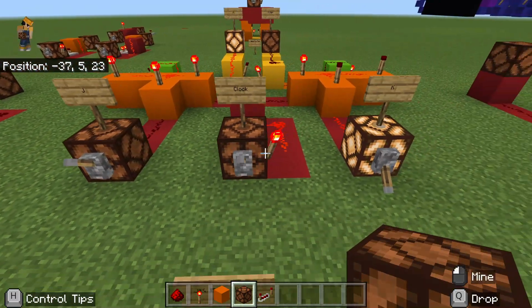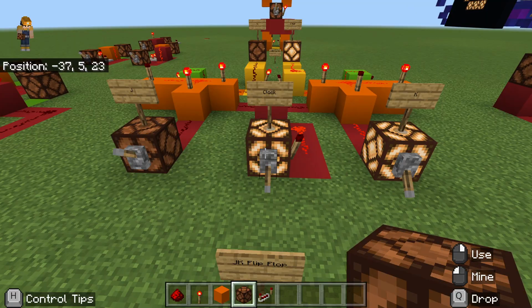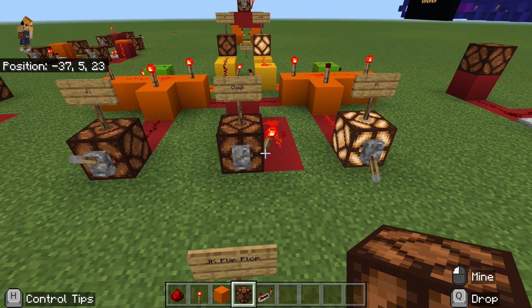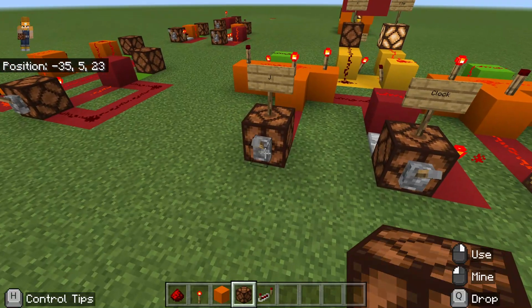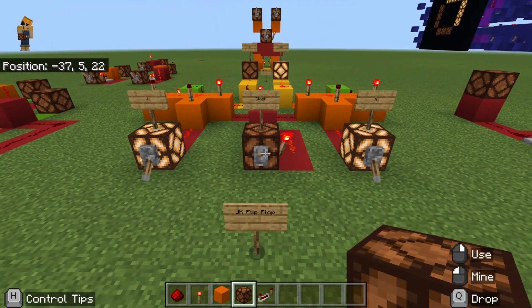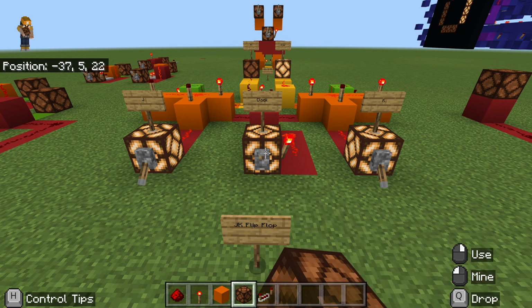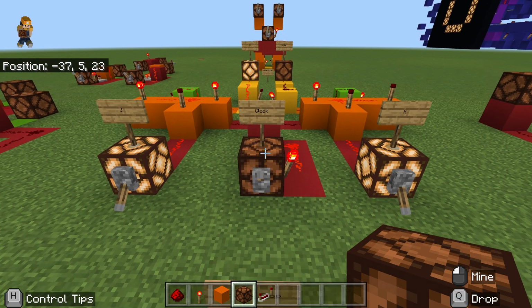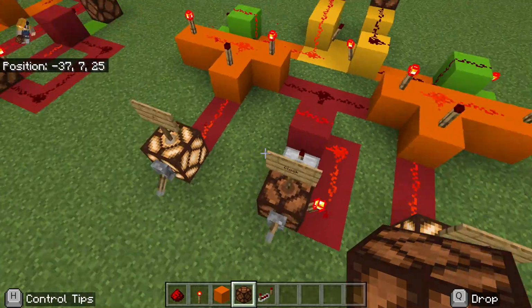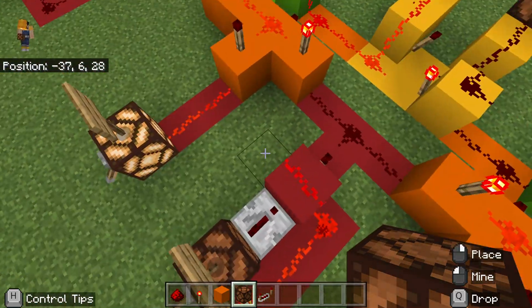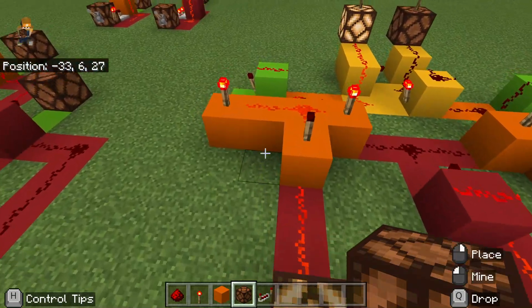And then if I turn K on and J off, it's going to switch to Q bar being on, no matter what I do with the clock. And then when I turn both on, it's going to swap each time. Q and Q bar, they just swap each time. So what this is, we have the clock, which is a monostable circuit.